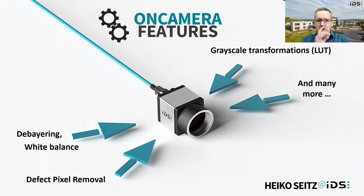Before that, it is important to mention how UI Plus cameras differ from their previous models. This is because standardization demanded an important change in terms of the camera's range of functions. In order to make the UI cameras independent of the PC software and responsive to any standard vision software, the complete feature control for processing the raw sensor data had to move into the camera.